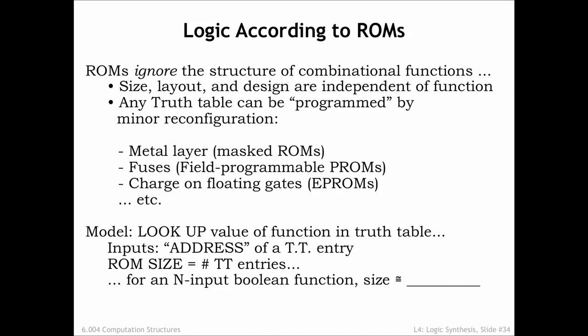Read-only memories, ROMs for short, are an implementation strategy that ignores the structure of the particular expression to be implemented. The ROM's size and overall layout are determined only by the number of inputs and outputs. Typically, the switch matrix is fully populated with all possible switch locations filled with an NFET pull-down.